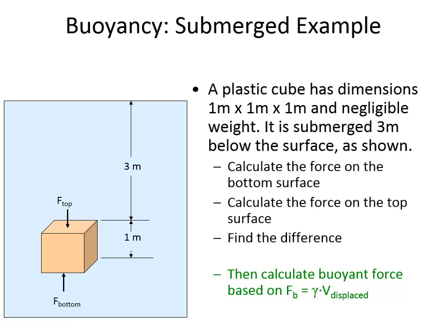So will it float? Will it sink? It depends on what the weight of that object is. If that object weighs less than 9810, it's going to rise to the surface and float. If that object weighs more than 9810 newtons, then it's going to sink.